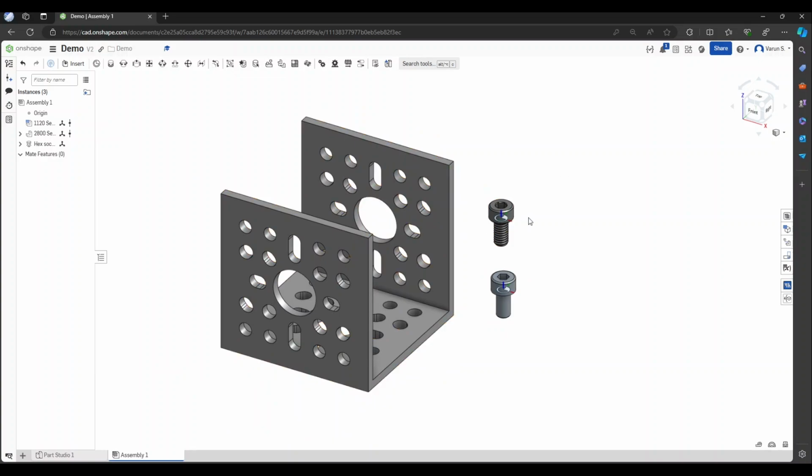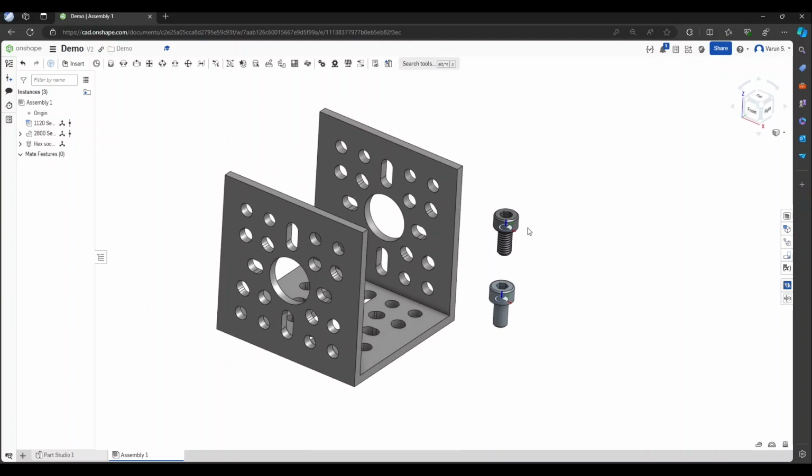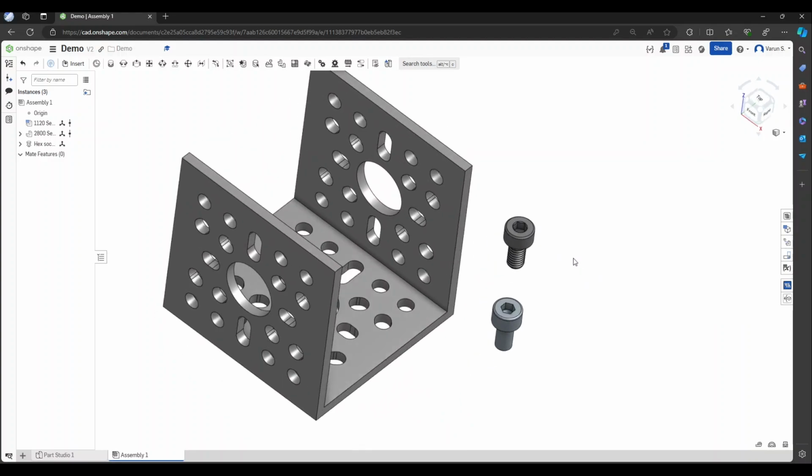The first thing you might notice is that these weird mate connectors are showing up, and you'll figure out what they are later, but basically, for now, we can just hide them. We don't really need to use them. So we can right click and then say hide all mate connectors, or you can hit the keyboard shortcut K, I believe. Yeah, that's what it is. So K, that's the other option you have there. Okay, but anyway, we have this stuff going around here now.